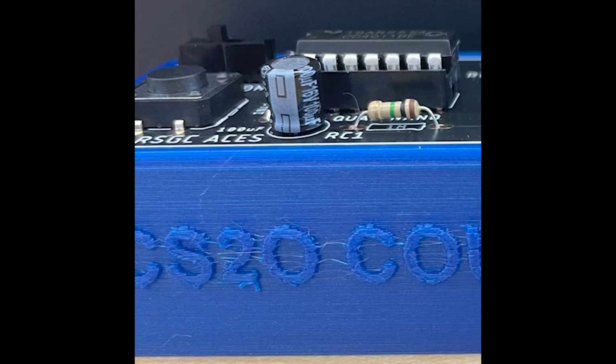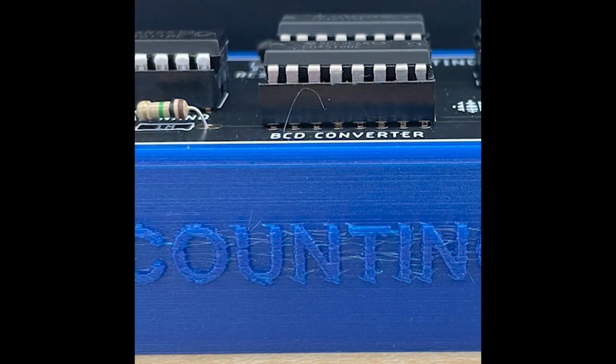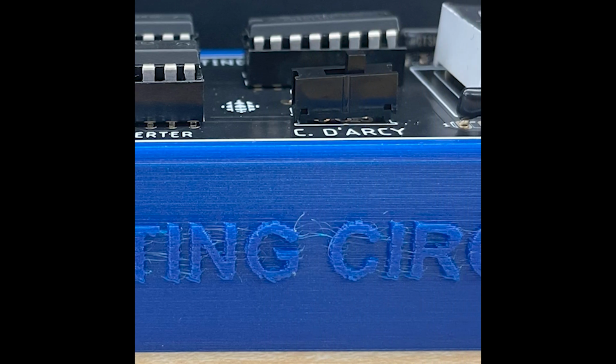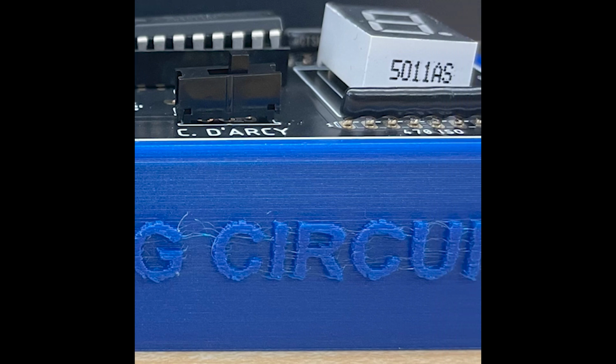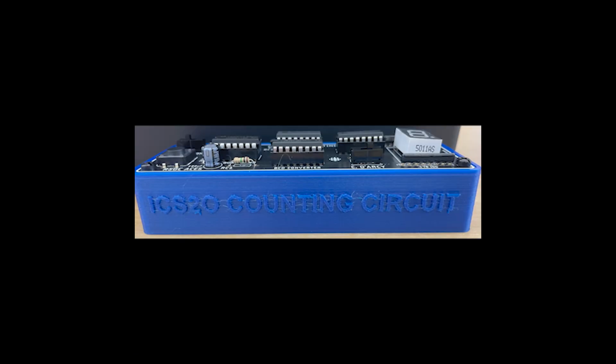The final step in our journey is housing all these components into a carefully designed case. The case not only physically protects the circuit, but also makes it compact and portable. One of the main challenges during the assembly process is to prevent the shorting of the PCB to the battery, which is resolved by carefully placing electrical tape on the battery.